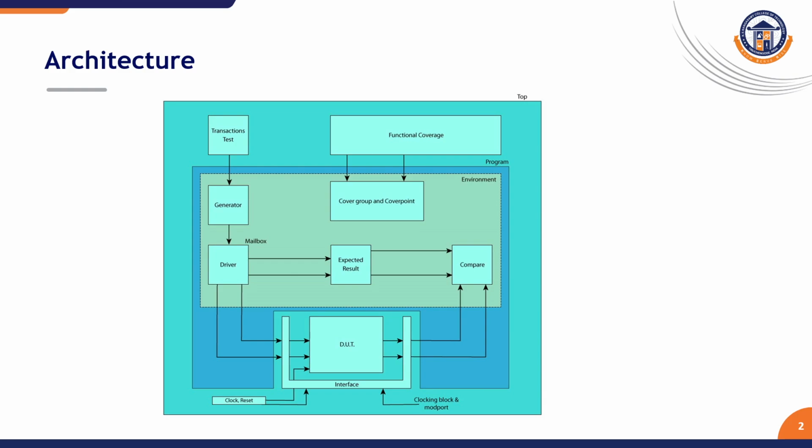So the transaction is nothing but a transaction class that helps with top level executions. It provides the important information to the coverage model about the generated stimulus. The transaction class also helps to define activities generated by the agent. It drives it to the DUT and returns back to the driver. So when you see here, the driver is connected with the DUT. All activities are covered under the transaction class. So that is the main purpose of the transaction.